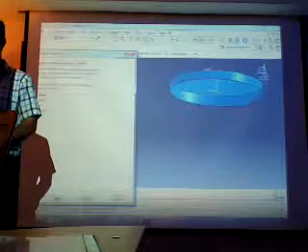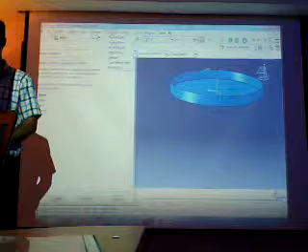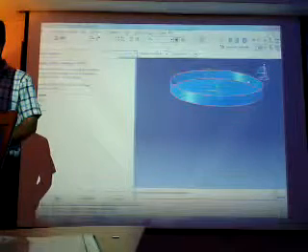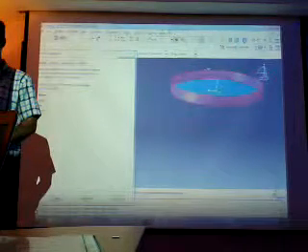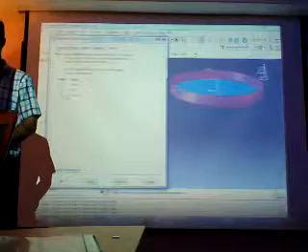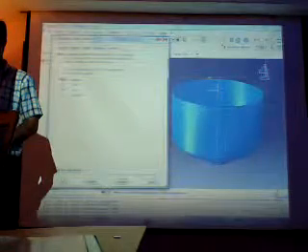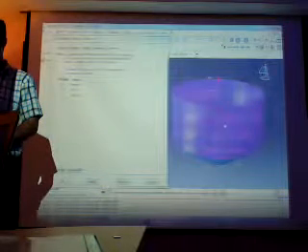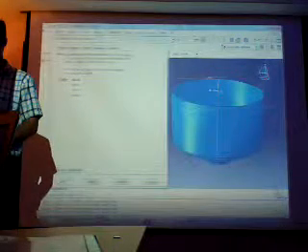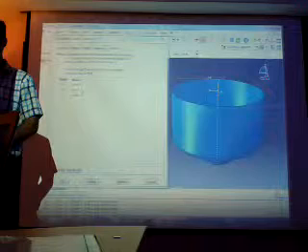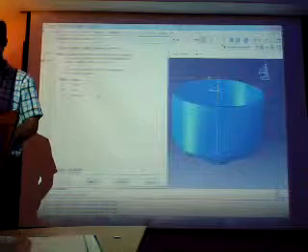First we are going to make it coaxial, in constraint, coaxial. Take the first cylindrical surface, hide this one, unhide die, apply, take this one. Okay.